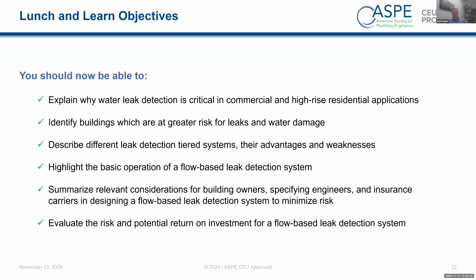And so, if you're not in that location, how is your machine going to learn the normal water use of that system? When you look at the algorithms that people use, it typically takes 1,500 events to learn the system. And again, like I said, if you learn the system when it has a leak, it's just not good at all. So you have to determine that you don't have any leaks, your pressure is holding, everything is good. Then you set the thing potentially on machine learning, and the system's not going to work for 30 days, 45 days.